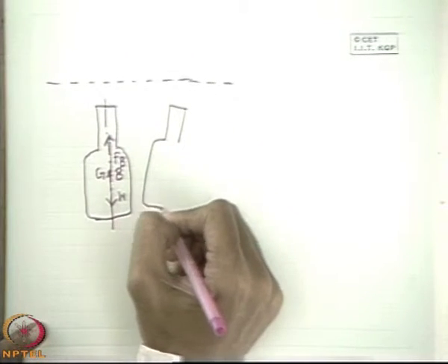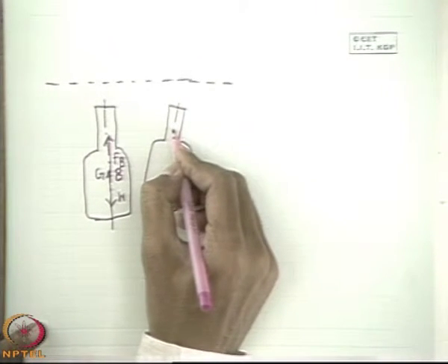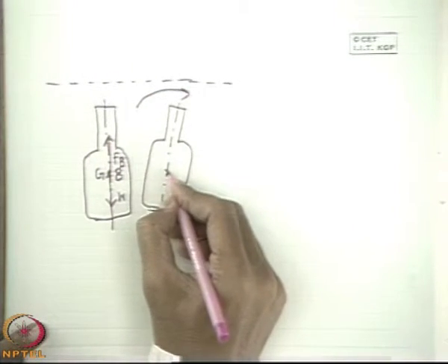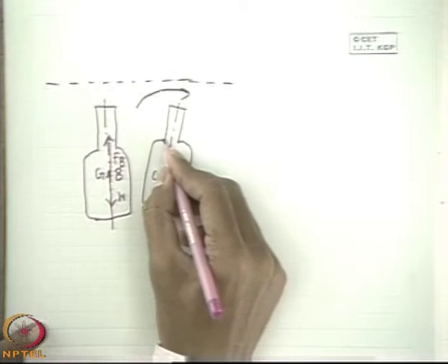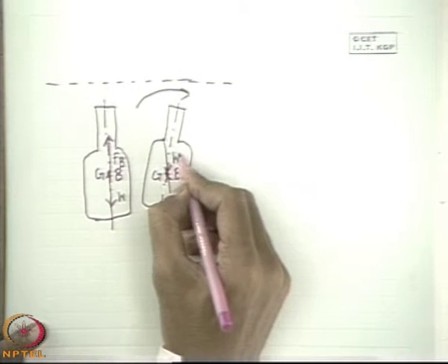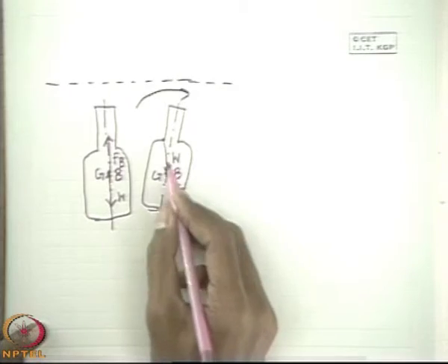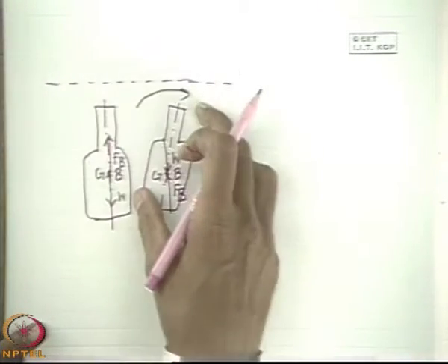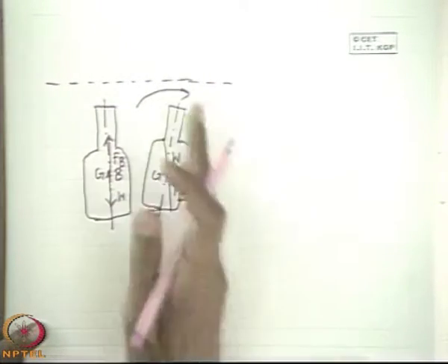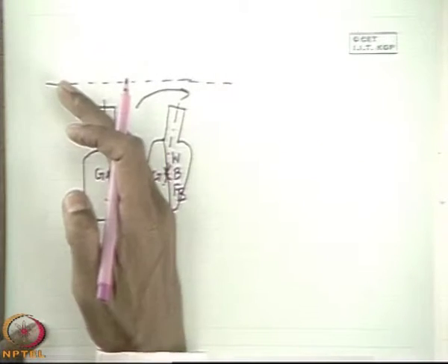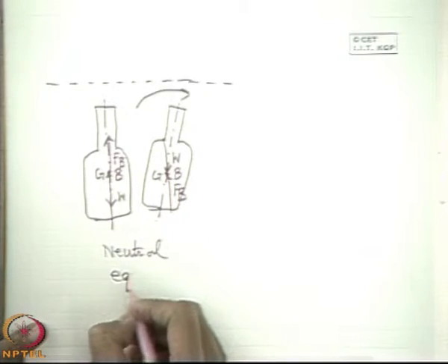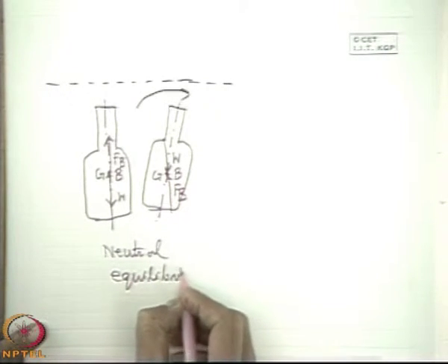That means if you displace this, if you give an angular heel in this direction, G and B both will be the same. So these will be the new vertical lines and they will be again collinear. This is W and this is FB. So it will be again collinear. That means at any angular location and at any angular displacement, it will be in equilibrium. It will neither go further in this direction nor come back in this direction. This is known as neutral equilibrium.